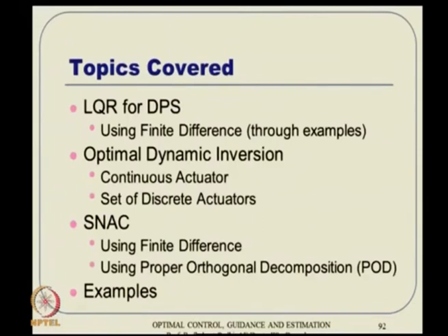But you can also have this idea of invoking model reduction through basis function design using proper orthogonal decomposition ideas, where you start with a set of snapshot solutions, and utilizing the snapshot solutions you can design basis functions which are tailor-made to that particular problem. Those basis functions are then utilized in Galerkin approximation to come up with a low-dimensional ODE representation of the system dynamics, and utilizing that ODE model you can come up with a state feedback control design. The details of that can be seen in the particular lecture. We have also given examples along the way.